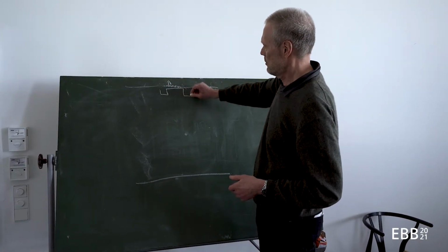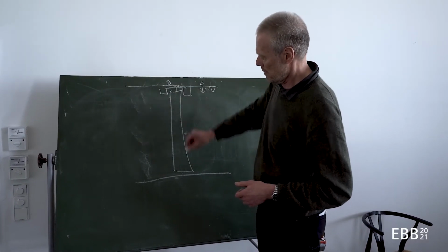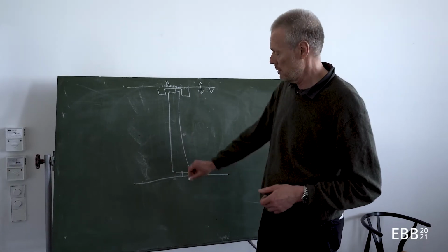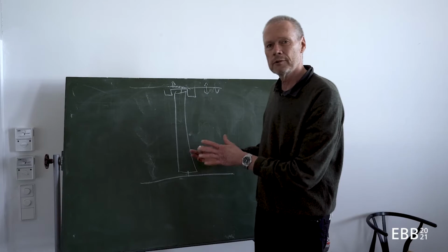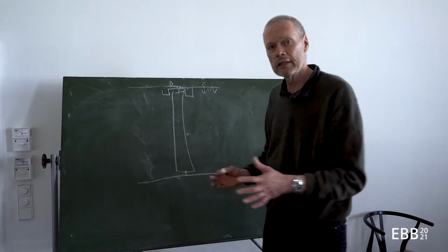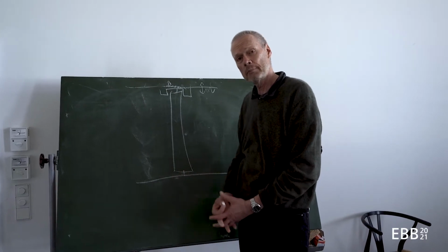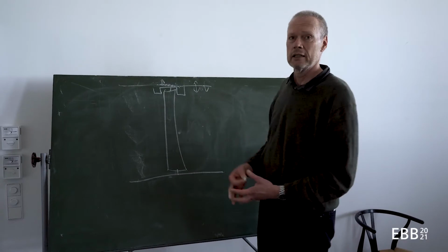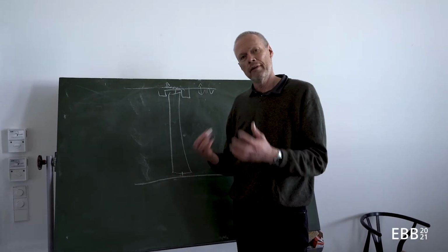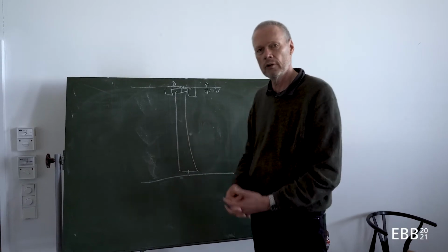If I have bending here of, let's say, 2 to 3 centimeters, particular attention has to be paid to sliding walls, because the sliding walls have to close tight on top and at the bottom, but I have to be able to slide them nevertheless. So if this is bending, the wall might be touching the ground. So in this case I have to limit the bending to a value that my type of sliding wall can take.